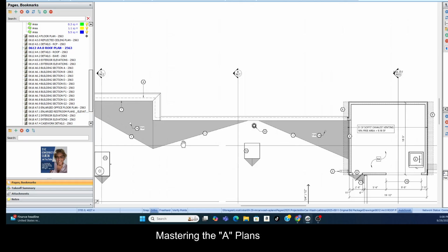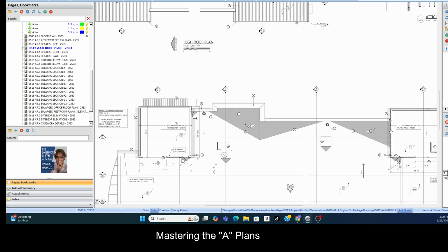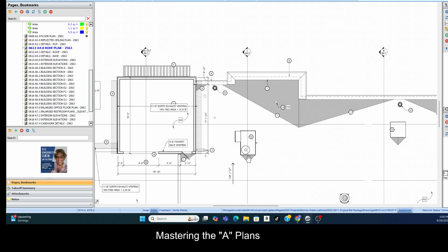Crickets are usually in areas of the roof that are really flat, so we put some roofing at an angle, where it'll be higher here than down there. It almost looks like it's tilting, so water will get out of these almost flat corners and go into the gutters. Okay, so that's additional framing over the flat framing in order to produce an angle to let that down. So it's usually in the areas where the roof is flat or water may sit, here at the rooftop unit.